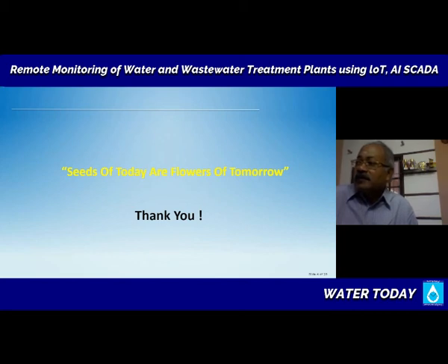Now, my suggestion is the most simple way is to operate in a batch mode rather than a continuous mode. What that means is, for example, every half an hour, you open a gate for 5 minutes and close it. Instead of trying to keep the gate open 20%, for instance, and then you are depending on the gate feedback. And if that feedback fails, then you don't know what is happening with your control.